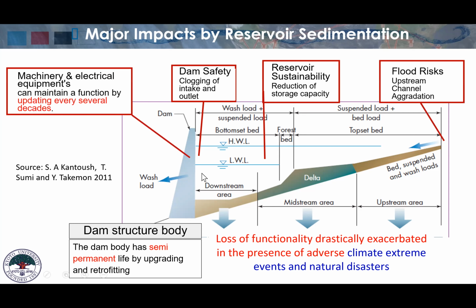An important issue in our river basin is dam safety, or the safety of the system itself, and how to create reservoir sustainability. Reservoir sedimentation will reduce the original high water level. When you have too much sediment, it will take 10%, 20%, 30%, or even more than 80% of the volume available for flooding and management, and it will be filled with sediment.